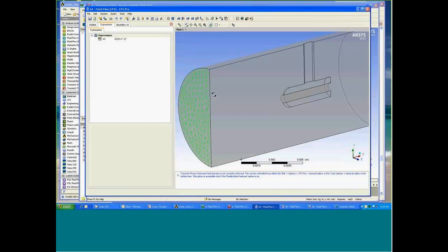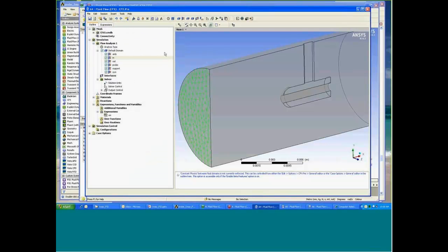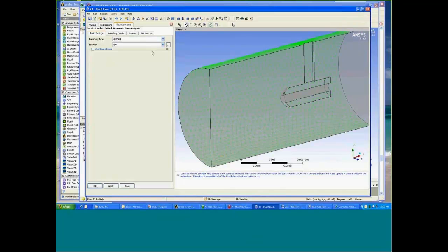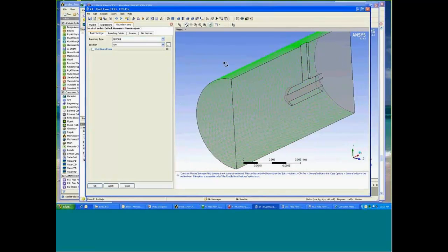Right now, it is 20 meters per second. So I have roughly a 20 meters per second wind coming at the probe, which is roughly about 40, 50 miles per hour wind, a pretty strong wind already, okay? And in a similar manner, I set up the outflow boundary condition and the ambient condition. That will be the cylindrical surface of the external flow domain, which I'll just assume is an opening, free to go in and out on these surfaces.